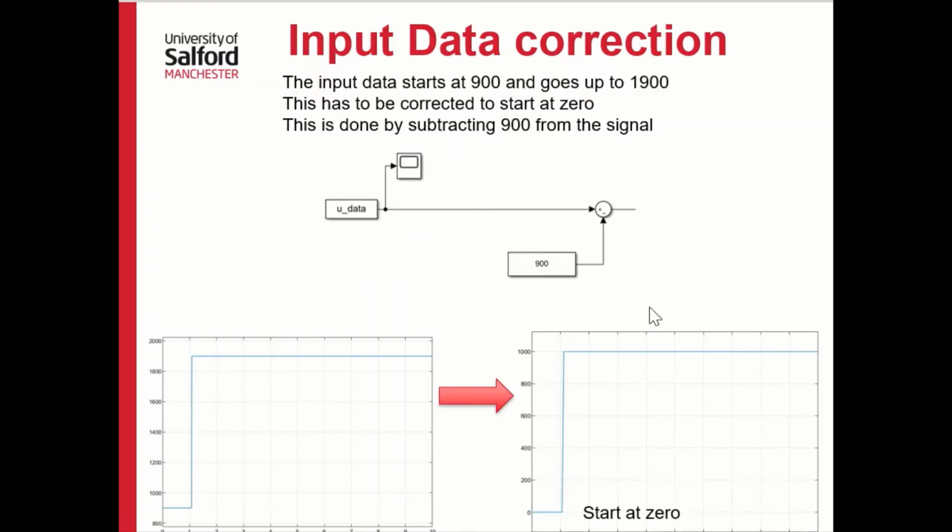The first thing we do is look at the output coming from the U data here, and we want that to be 0. If we put a scope on at the moment, it starts off at about 800 and goes up to 1800. We want to start at 0, so I'm going to put 800 in here with the plus or minus, and it'll bring this down to 0. So the signal here should look like this, and we've now got a 0 start on our input.